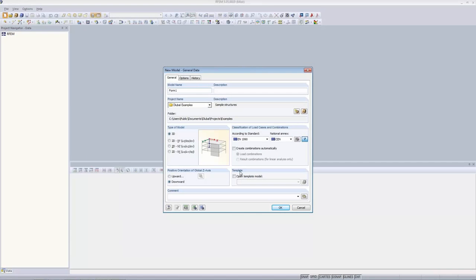Here we go. So we start with the first example. I will show you first two quite easy examples, maybe that's not the right word. It's two examples which demonstrate the two different calculation methods, the tension method and the projection method. And I will show you advantages and disadvantages of the methods. After this, I show you a bit more complex structures, also membrane structures, and at the very end we will have a look at one cable example today. So you will see five examples during the webinar today.